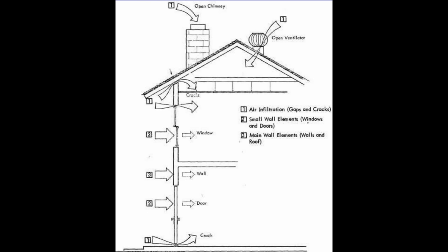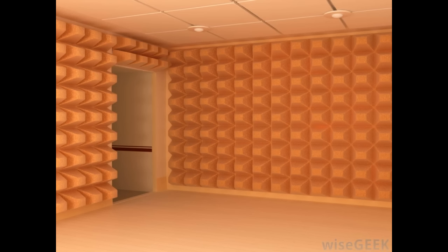I'm going to cover all those types of things. Caulking, green glue, special acoustic treatment for various situations, without getting into fully covering your walls with foam, absorptive foam. You can actually make a room too dead to sound, so that would be a very uncomfortable situation also.